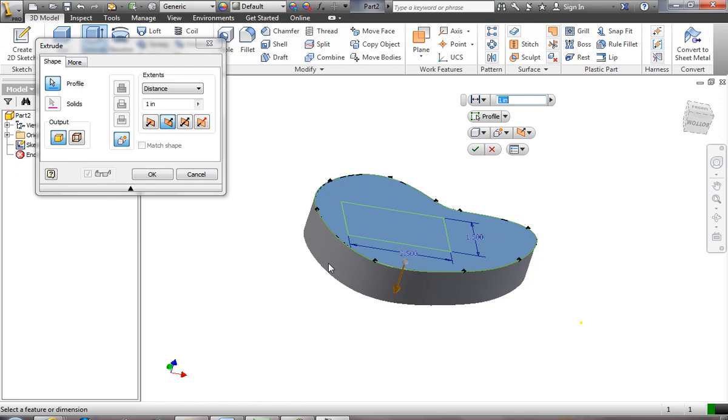So this outside face needs to have a draft angle that's skinnier on the top and fatter on the bottom. So the wall of this soap dish is going to go down from the top in the shape of a trapezoid. If I were to measure the very bottom edge from here to here, it would be more than the top edge from here to here. We do that with a draft angle.